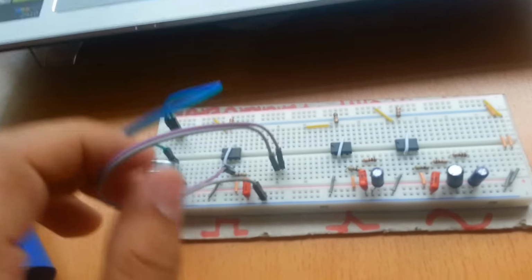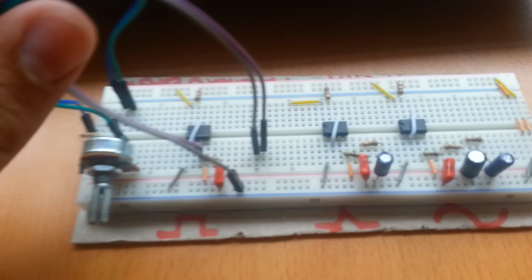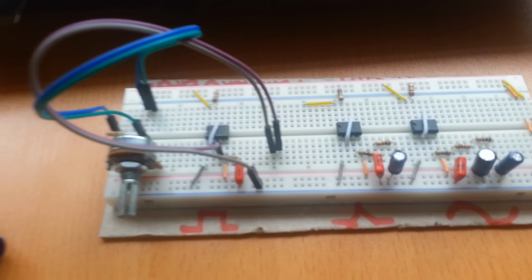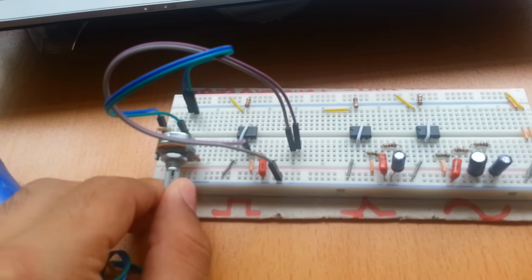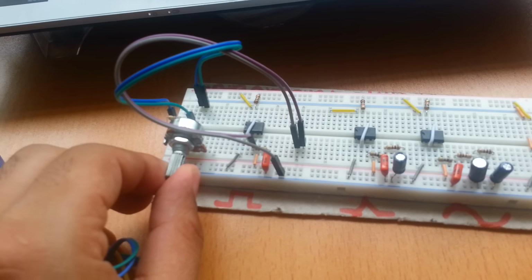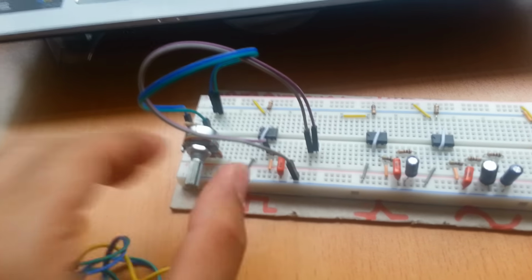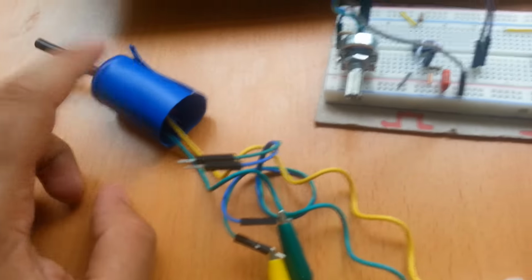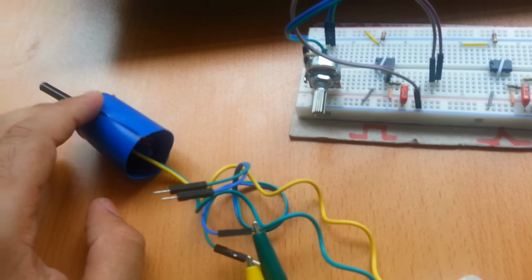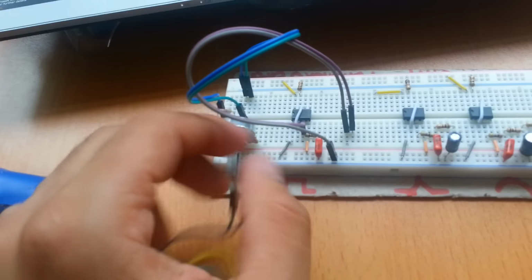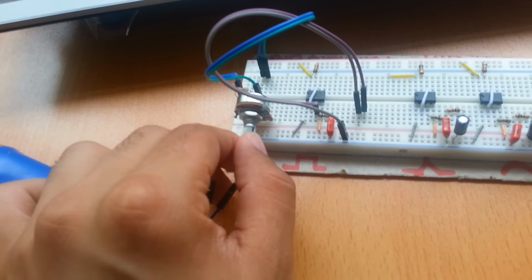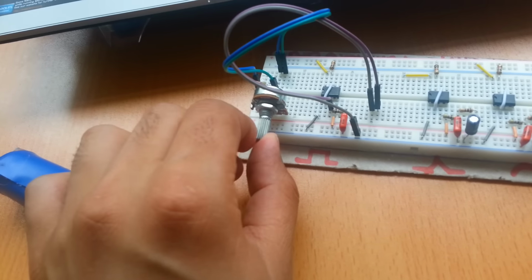So now what to do to get values in each interval alone? In each individual interval, we use this potentiometer. Very simply, you can get any value. For example, if I connect the capacitor of value 1 microfarad, then I can get from 1 to 10 hertz very purely.